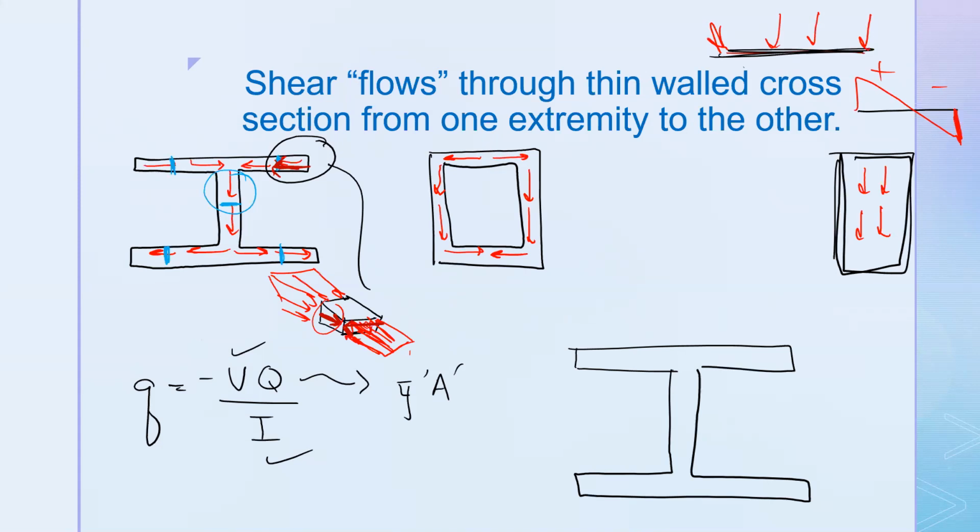When we're taking our section cuts and we're going a little bit farther and a little bit farther until we get to this midsection, y-bar is the same for all of that analysis. So this is our centroid. y-bar is always going to be measured to the center line of that flange, but your area is increasing.